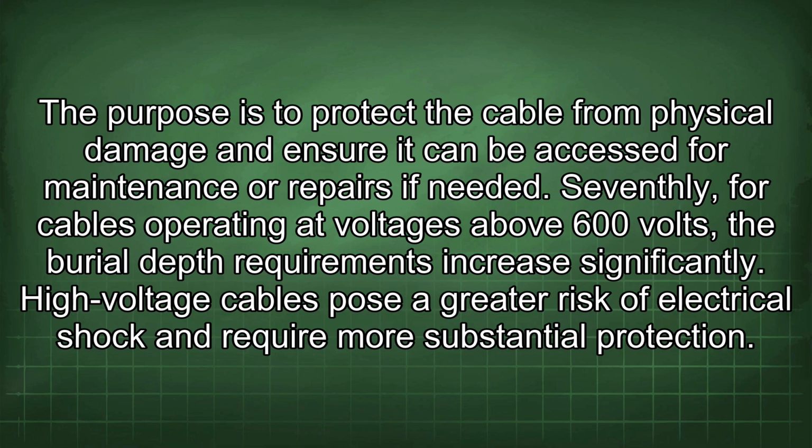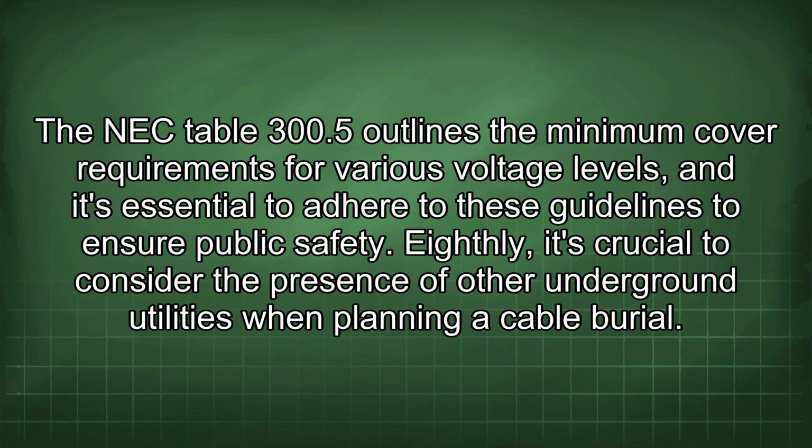if needed. Seventhly, for cables operating at voltages above 600 volts, the burial depth requirements increase significantly. High voltage cables pose a greater risk of electrical shock and require more substantial protection. The NEC Table 300.5 outlines the minimum cover requirements for various voltage levels, and it's essential to adhere to these guidelines to ensure public safety.